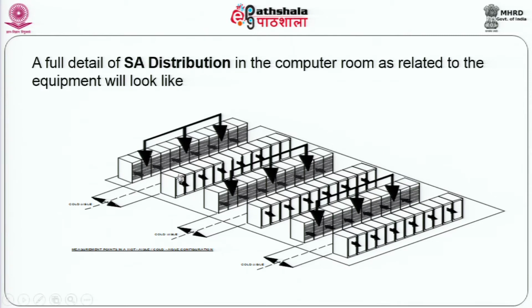In other words, you find something like 60 laptops being kept here, and the heat from all those 60 laptops is liberated within this. Now, as we looked at in the earlier slide, one could open up a small amount of space here for supply air to come from the underfloor device and get into this rack, and hot air could get out over the false ceiling. I hope it is easy to correlate what we saw with the simple cross section onto this complex section.